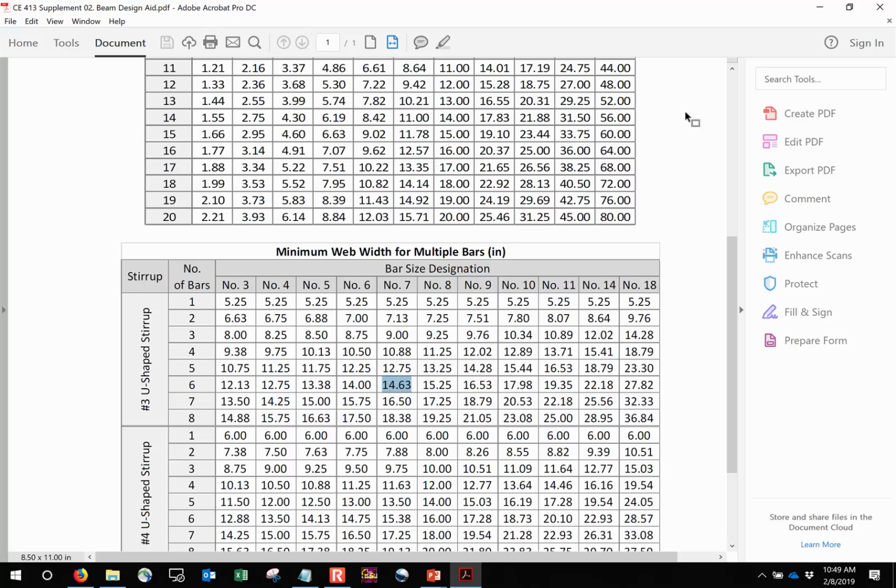So that was going to be my question, is the height. What do you do if you add more? What I would probably do in design mode, if I just needed a rough value, is add maybe another 1.5 inches or 2 inches for every other layer. But then when it was all said and done, I would look at my rebar pattern and see if I could squunch the bars up and maybe cut a little bit of weight, but I would do that at the very, very end. Are there any other questions?